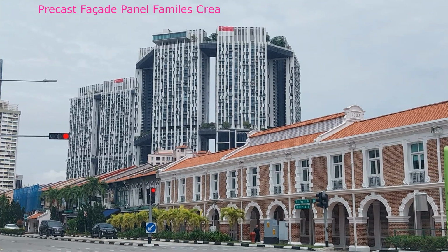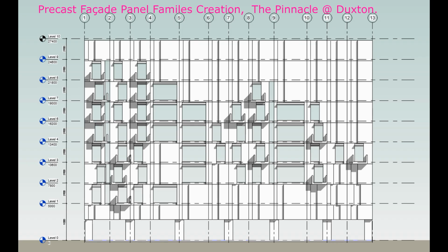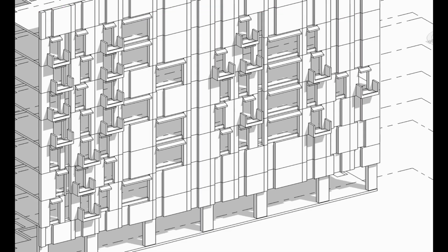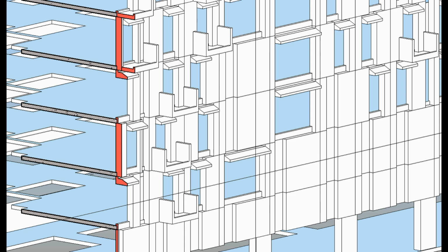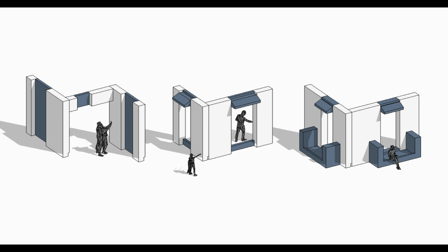And in conclusion, 1. Back up your families and project to ensure that all changes are secure. 2. Review the overall visual quality and ensure that the new families are integrated correctly into the model. 3. Consider creating any additional family types for variations in dimensions, such as for different floor levels or building sections.